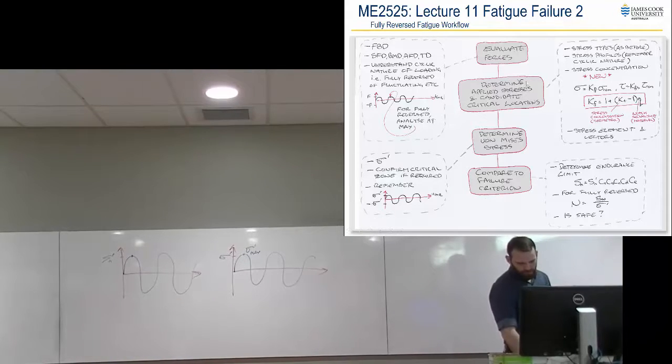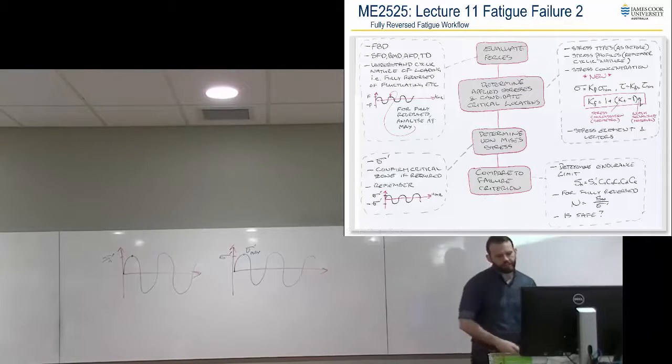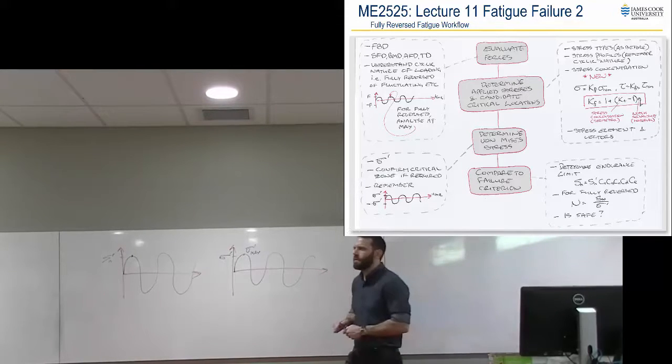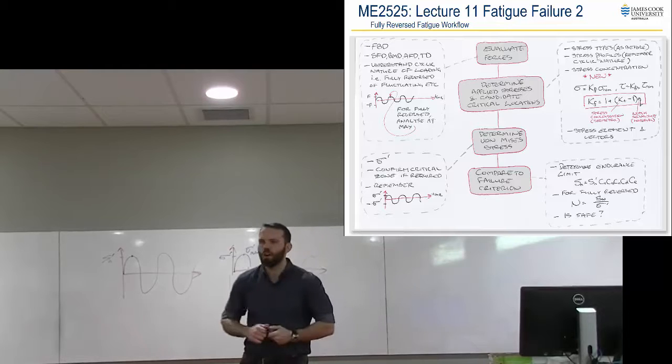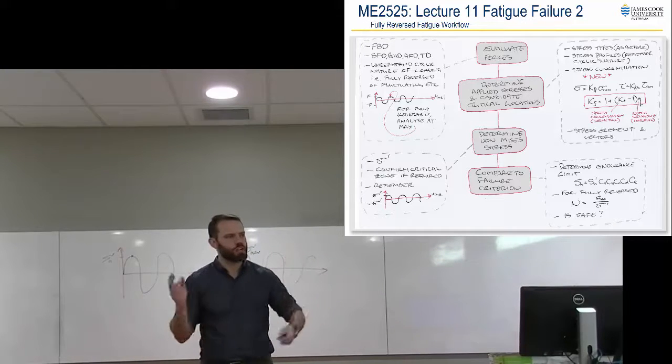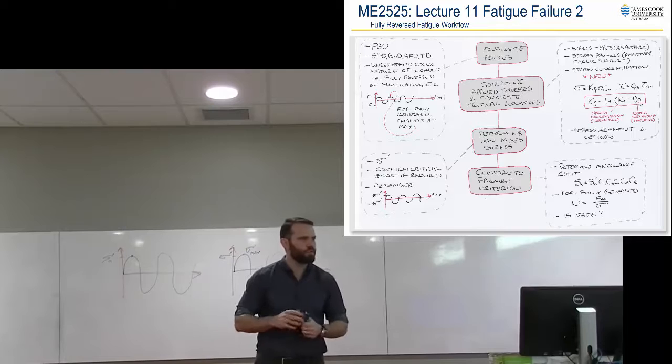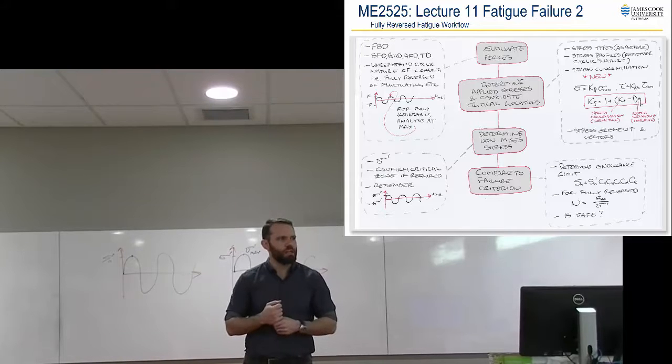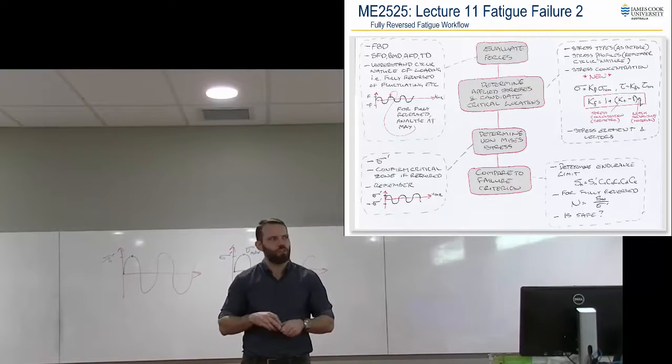Next thing, determine the applied stresses. Exactly the same as before. Alright, so we know stress types are available: bending, shear, transverse shear, torsion and so forth. We can use exactly the same stress profiles, except we need to remember that it's cyclic.